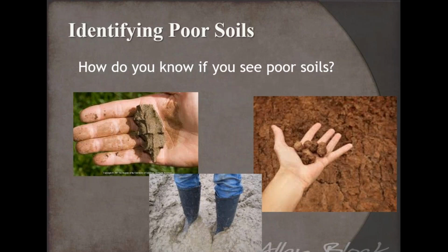But if I grab that soil and I squeeze it, and it tends to hold the shape of my palm, we know we're talking about a cohesive soil, with some fine aggregates there. Obviously, when it gets too wet, in that picture down on the bottom, you're standing in mud, and that's kind of a liquefaction where it's behaving more like water than soil, and there's no way you're going to get stability with something like that.